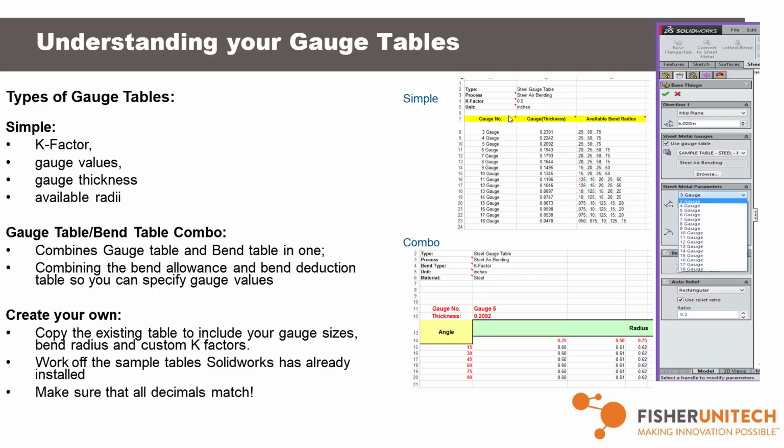I do machine design. I'm going to bend up a 90-degree bracket. I'm going to put a Keyence laser sensor on, and it's going to detect a part. If I use the K factor for 12 gauge sheet metal on a piece of 7 gauge, it's not going to come out the right height. I'm going to be off by 1/8 of an inch. When you bend 20 brackets in the machine, and someone pays to have them laser cut and bent, and none of the sensors hit, I tell you that's a real fun phone call.